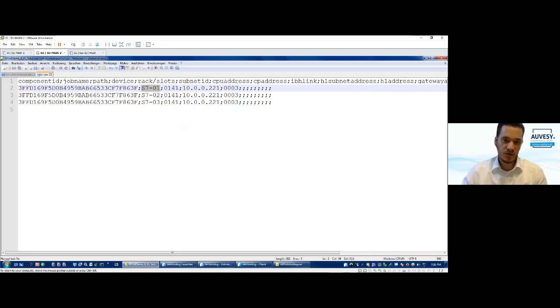And then in case of an S7 job, it is necessary to set up the access path to the device, and then the IP address of the device and the rack and slot from the CPU. As you can see, we have more options to set up, but in this basic example, I will show you in an easy way.